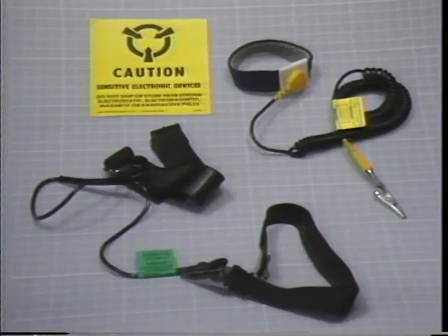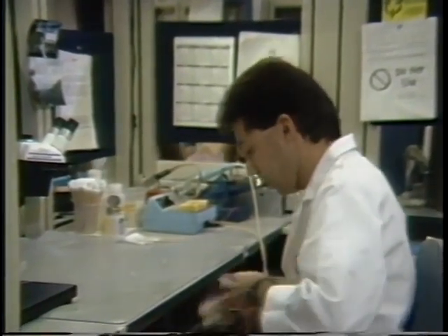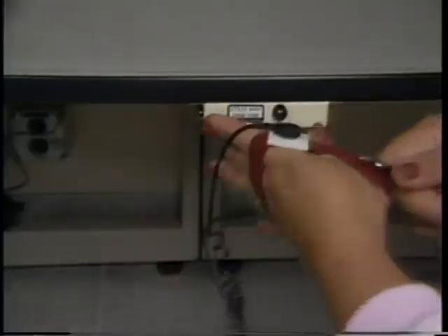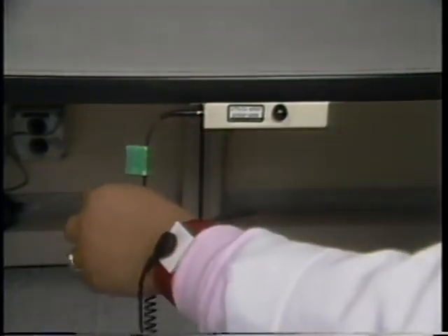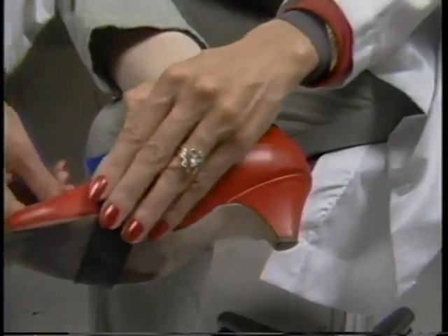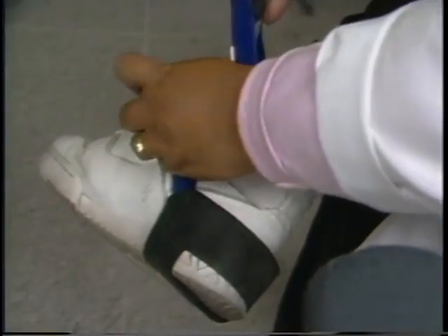You should see a valid certification label on all equipment, including the wrist strap and any special equipment used for processing work. But the most important step before beginning work at your station is to attach your wrist strap. The wrist strap prevents static buildup and allows you to handle ESD-sensitive hardware safely. The leg strap also prevents static buildup when used on an ESD floor. But unlike the wrist strap, it allows you to carry unprotected ESD-sensitive hardware away from your workstation without damage.